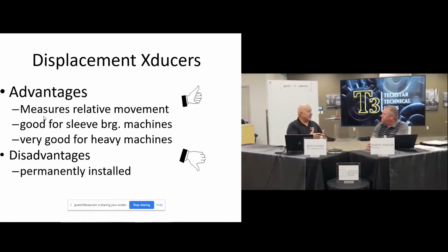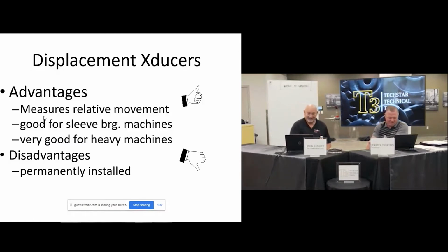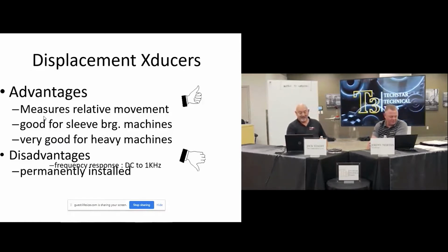And then they install the machine and run it, and they start having vibration issues, and they don't understand. Then you go there and you find out they never field adjusted once it was installed. I've seen that, yeah. And I've seen the opposite end of that, where they made contact during shipping and damaged probe tips as well, and scratched the burnish area. People always ask me, can we burnish the area while the rotor is in the machine? And I go, I've been wanting to figure out how to do that. Boy, if I could patent that, that would be great. So it's got to go in those V blocks back at the shop. That's right.